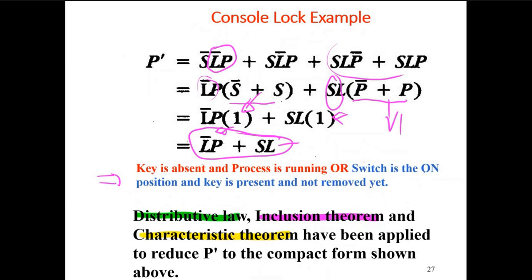That means operator came, switched on the process, got the process going by pushing the on off switch S to a on position, right, and walked away. So if somebody monkeys around with that on off switch, they can't do anything else. The key is not there. They can't unlock the console. They can only monkey around with the power switch. Your process should not be shut down. That's the first term that is making sure process is foolproof.